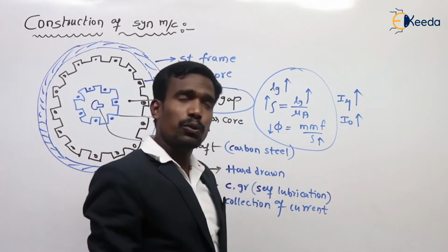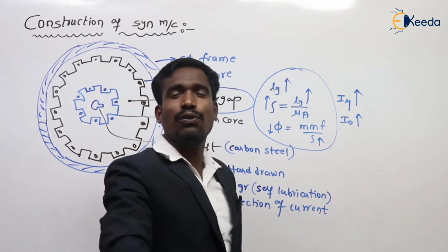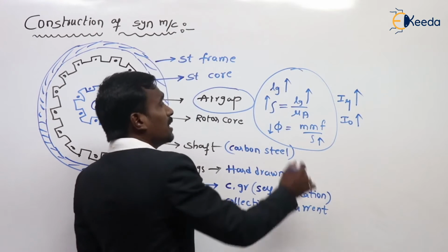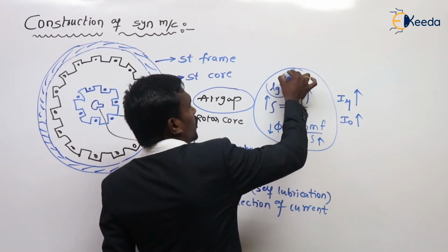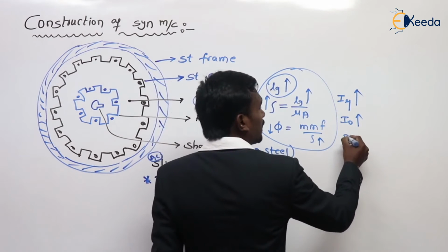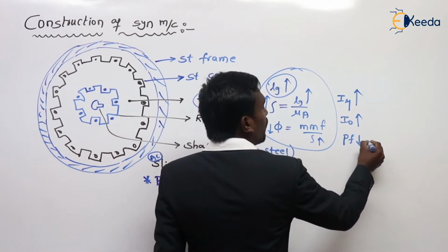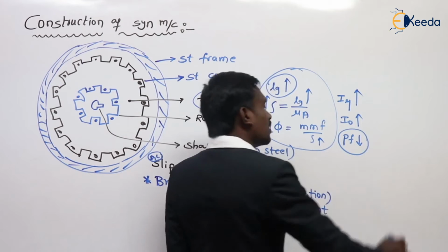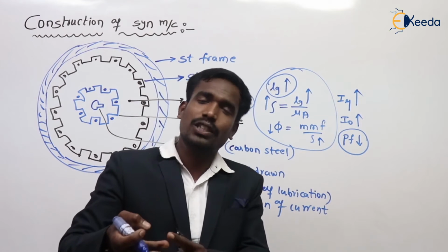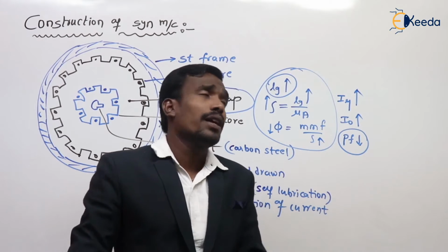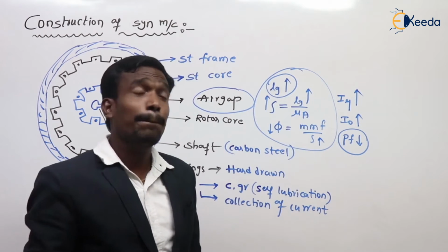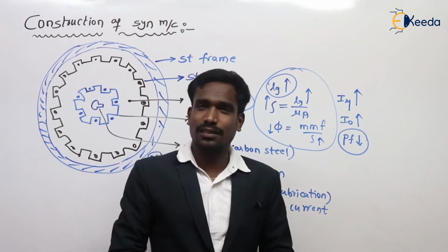This is the concept for transformer and induction machine. But in any electrical machine, if air gap length increases, power factor decreases. This is very important for transformer, induction machine and synchronous machine.